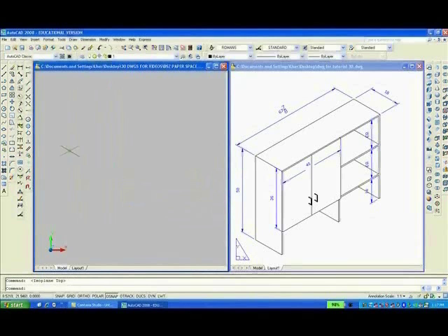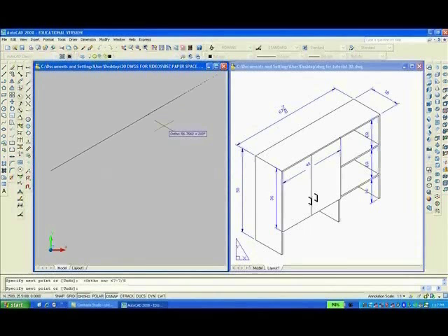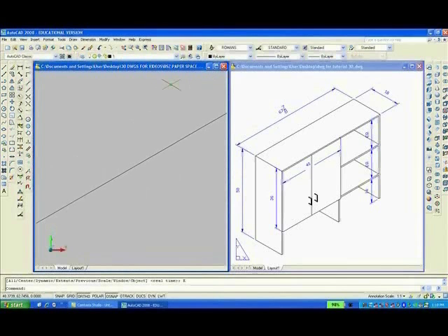So now we'll draw a line. That line will start here with ortho on. It'll go up 67-7/8. Enter. Z, enter, E, enter. Zoom extents. So now I'll shrink it down. And then I'll pan.